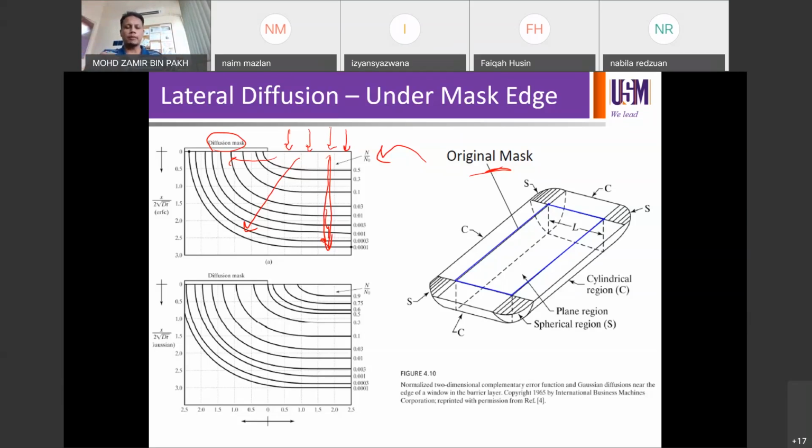If you talk about low technology node ICs, when the gate size is perhaps below 20 nano, when your MOSFET is really small, whether it's a MOSFET, FinFET or GAAFET, control of the diffusion profile becomes very critical.